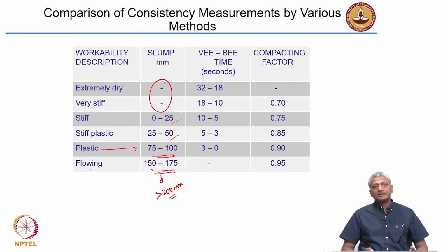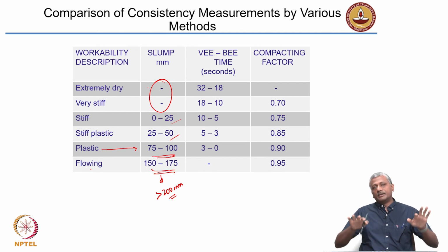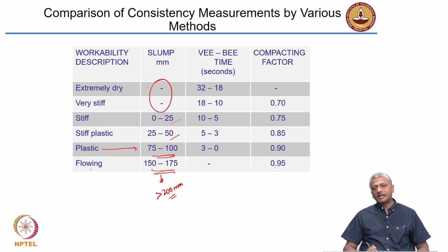When they place it, they will put a roller above it and compact it. That is one of the ways in which they do it. The other is they will push this through a extruder or a paver and then get the shape of the slab perfectly made. In such cases, the concrete is workable, too workable, the slab will collapse, and you don't want that to happen. So in such cases, you need to mold it properly.